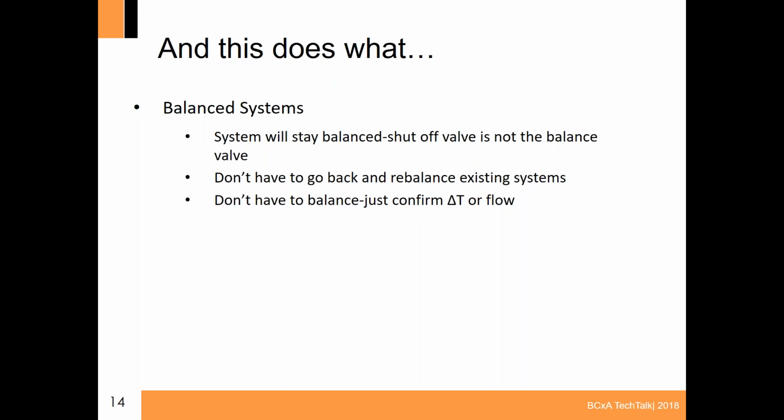The balance side of systems, okay? The system will stay balanced. I don't know how many times I've watched on jobs when I was working on the field side of things that the balance valve would be used as a shutoff, and then it would never get put back. I don't know how many times I've seen out there where they know they've got a little bit of a load issue, and most of these field guys, they'll go in and just crank open the balance valve a little bit more than what it's designed for to satisfy the load,